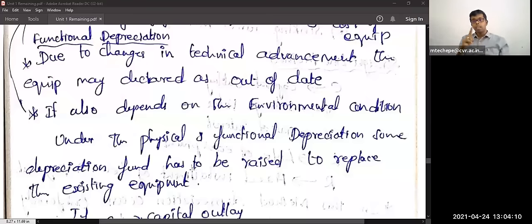With transmission lines running, you can't cover all of them with roofs, because over 300 kilometers, how will you cover them? A substation of about 1 acre, or some square feet, you can easily cover with a roof. But transmission lines of 300 or 500 kilometers you can't protect. So due to ice formation, sometimes you will get a short circuit. Sometimes it is due to the swing operation.